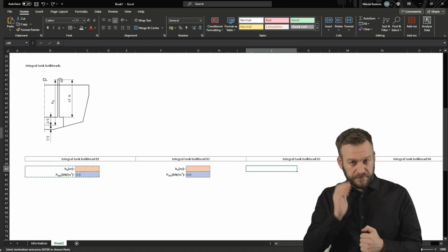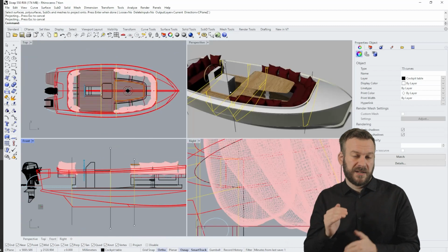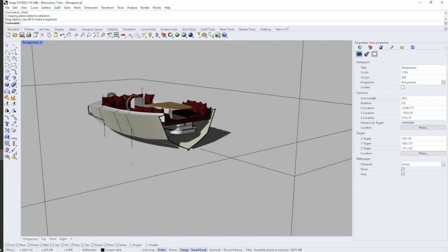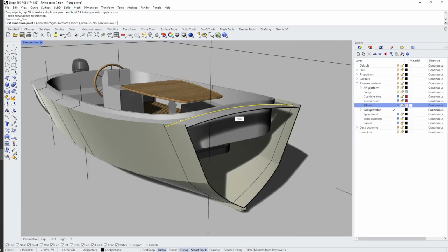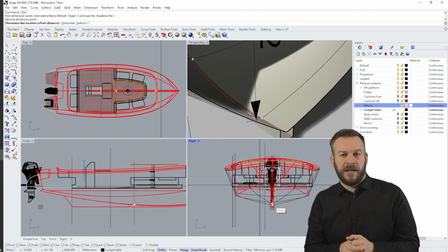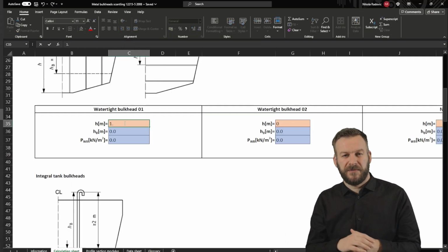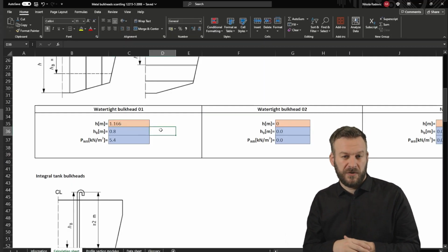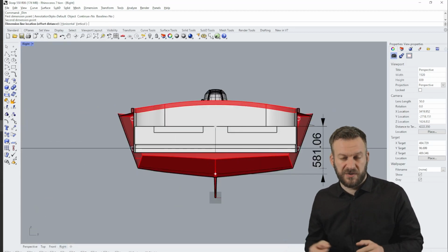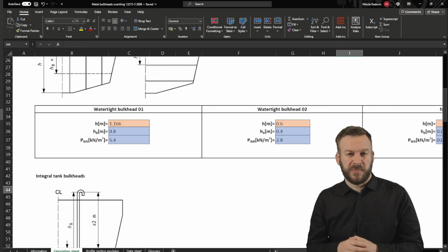And next step is to find dimensions, so let's open Rhino and measure it there. Collision bulkhead is the highest one, so I will first measure height there. And as you can see, we have almost 1200 millimeters of height, and that gives us roughly 5.4 kilonewton per square meter of pressure. Aft bulkhead is less loaded since we have openings on the seating position at approximately 0.6 meter. This gives us pressure of 2.8 kilonewton per square meter.